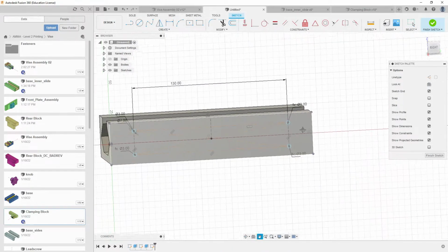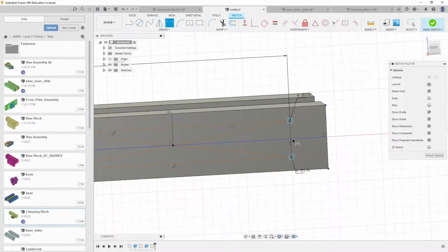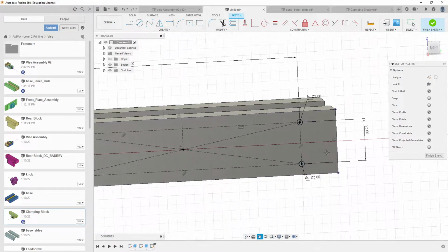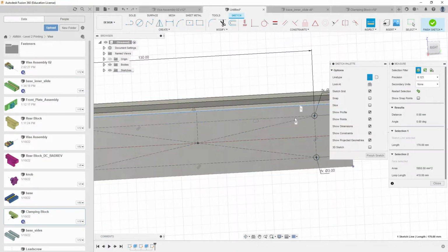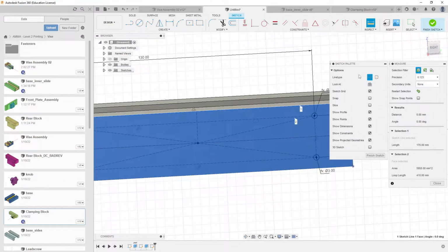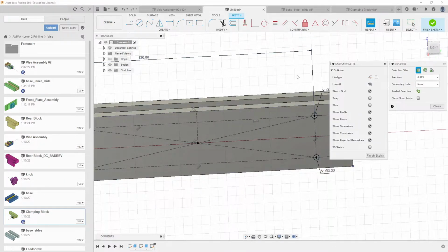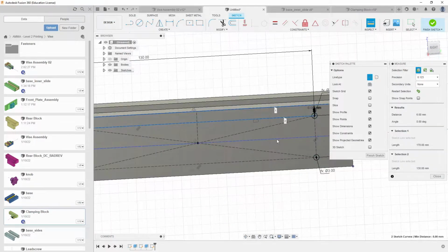Then the height over here, this is kind of interesting. The height is 23, so I can put in 23. But the way I originally designed it is to have a 6mm edge margin. Maybe not exactly a problem, but here I'll show you. If I were to inspect this, I go from this edge to right there, not the face. If I go from this edge right here to that line right there, 6mm, it's a symmetrical rectangle based off the center, so this one here is 6mm also.